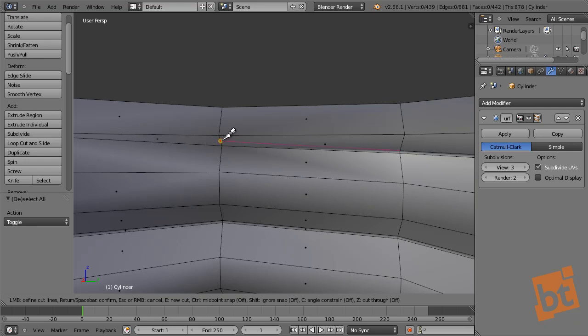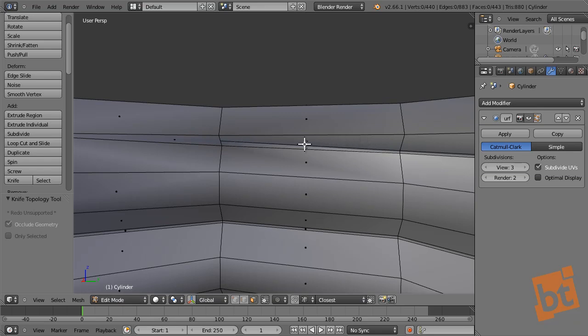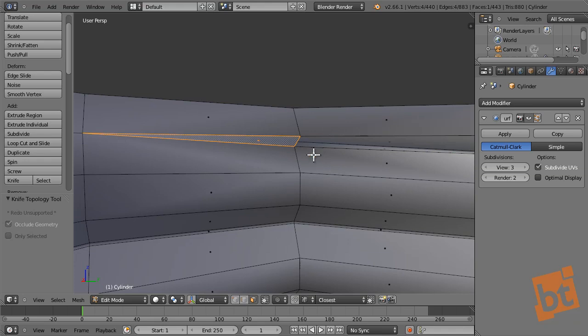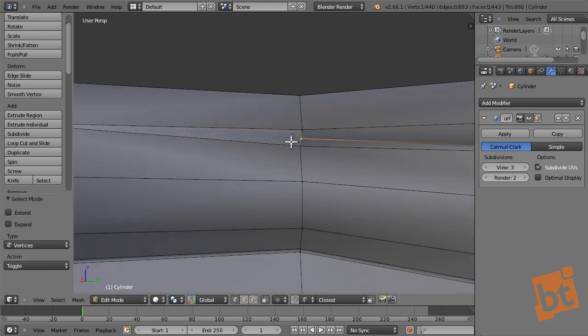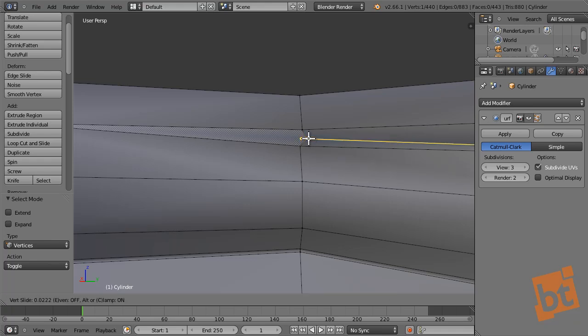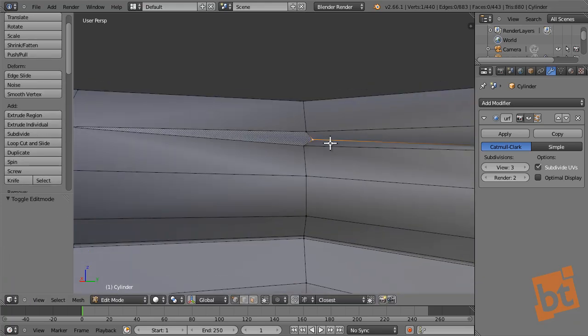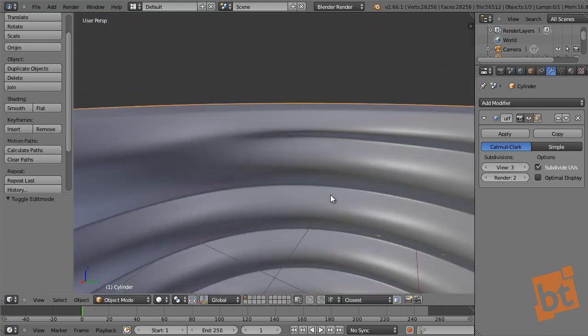Click and enter. So now, as you can see, we have 1 quad, another quad, and this is now a quad. Even if it looks like a triangle, it has 4 sides, right? We could just move this with Shift B through this edge to make it look more like a quad. So now that is a quad.